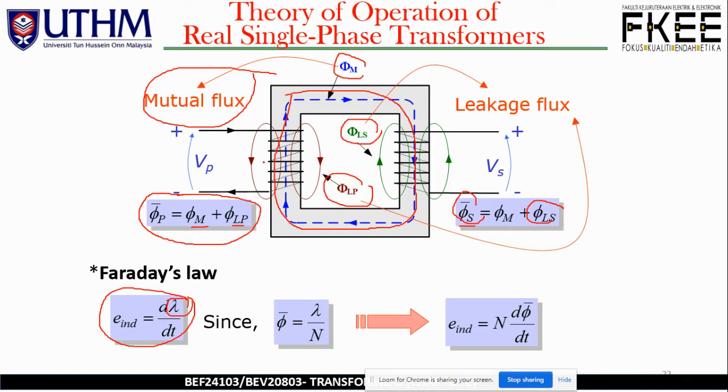It occurs in between the flux linkage across the coil, of which the voltage is being induced, and it is the sum of the flux passing through each turn in the coil. The average here is the average flux per turn, which is equal to lambda over N, and just rearrange.